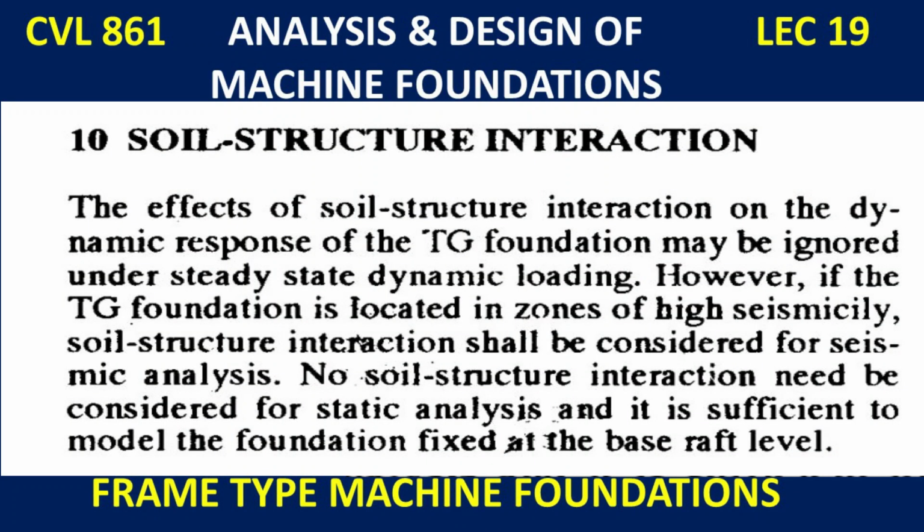The code says that effects of soil structure interaction on the dynamic response of TG foundation may be ignored under steady state dynamic loading. Steady state dynamic loading means when the machine is operating and we have steady state conditions, harmonic loading. However, if the TG foundation is located in zones of high seismicity, soil structure interaction shall be considered for seismic analysis. So in high seismic zones like zone 5, we need to do the soil structure interaction also, modeling the soil as springs. No soil structure interaction need be considered for static analysis.